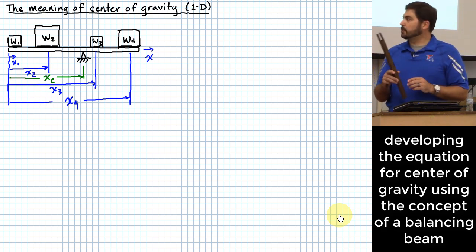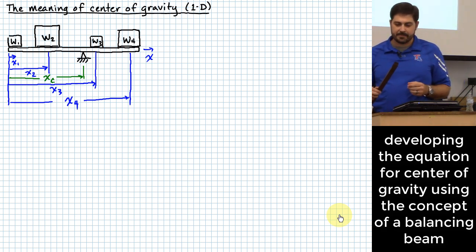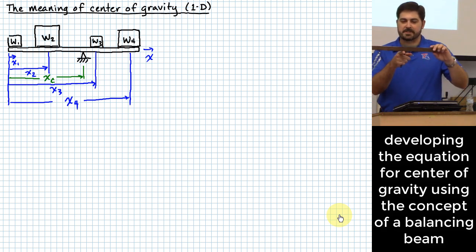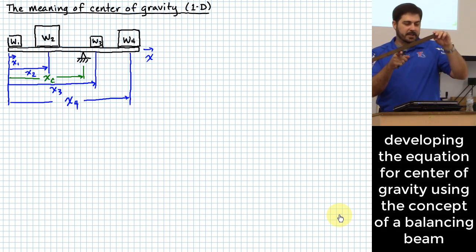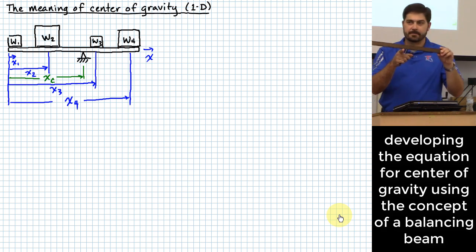And that's actually a really good way to get started talking about what it even means to have a center of gravity. What I'm doing there is I'm basically trying a few different spots along the length of this thing, and what I'm looking for is the place where all of the moment reactions that would tend to try to rotate it one direction perfectly balance the moment reaction that would try to rotate it the other direction, and that's when it'll balance on my finger, okay?